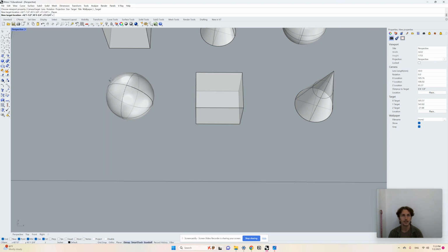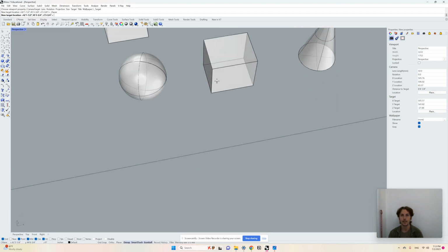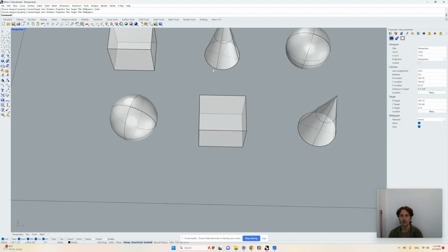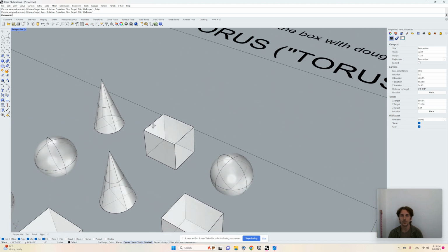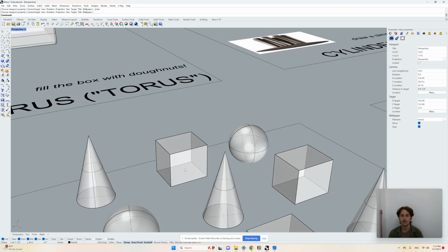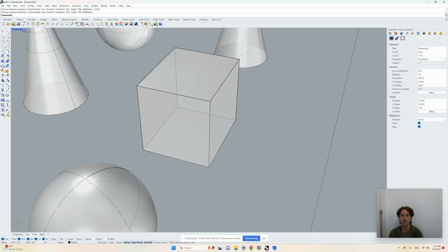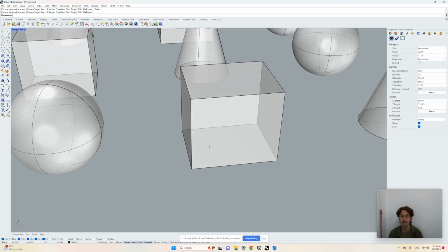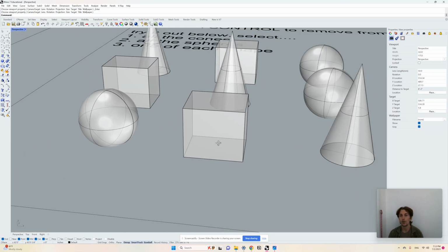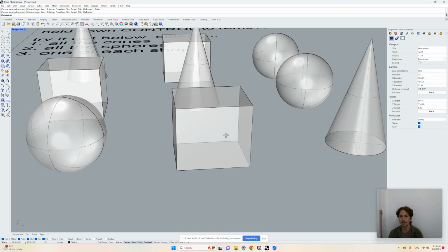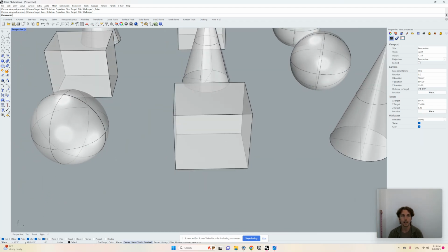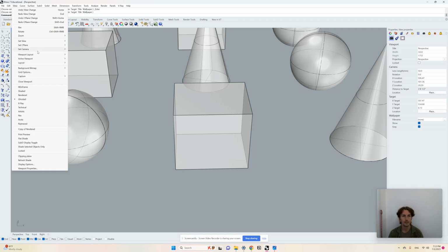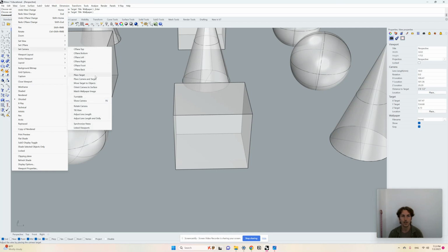When you place target, it's going to say New Target Location, and you click somewhere on the object that you're working on. So I'm going to click on this corner of this box, left click, and then that makes that the center of rotation. So now it's much easier for me to orbit around this box. And if I'm manipulating it, if I'm turning this into some kind of detailed cabinet, this is going to be so much easier than trying to zoom in and out and look at the part of it that I need to look at. So that is set target. It's View, Set Camera, Place Target.